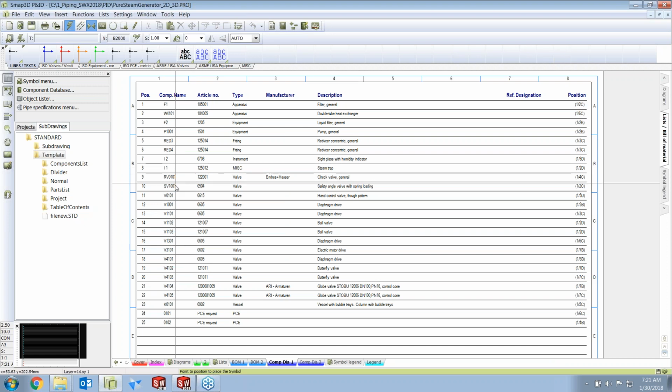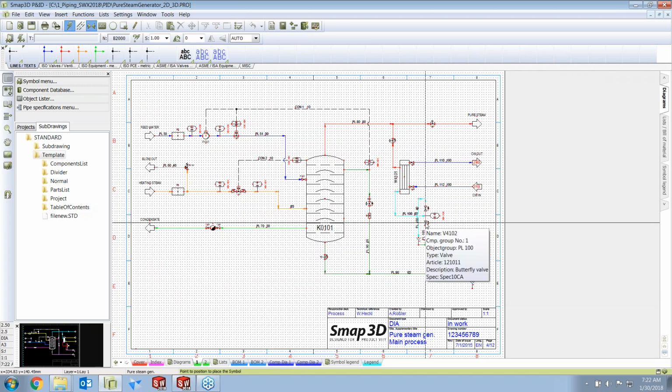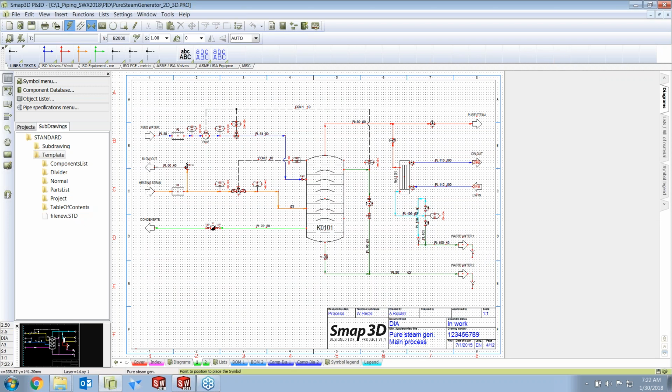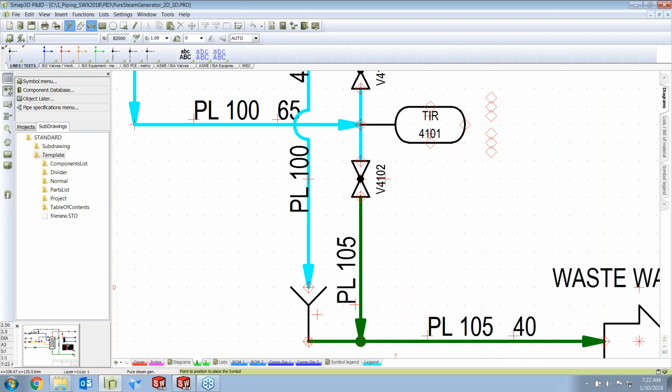Okay, so that we can identify if we use 1400 millimeter globe valves, all from the same company. Each one of those globe valves is probably going to be controlling a different process, a different fluid medium, or something of that nature. So we can break it down and show exactly what page, what column, and what row it appears on. It also makes it very easy to navigate and find something where we can say, hey, where's this 4102 butterfly valve? I just click on it, and it navigates to that page, and it puts my mouse cursor on that physical component so that I don't even have to hunt for it on that page.